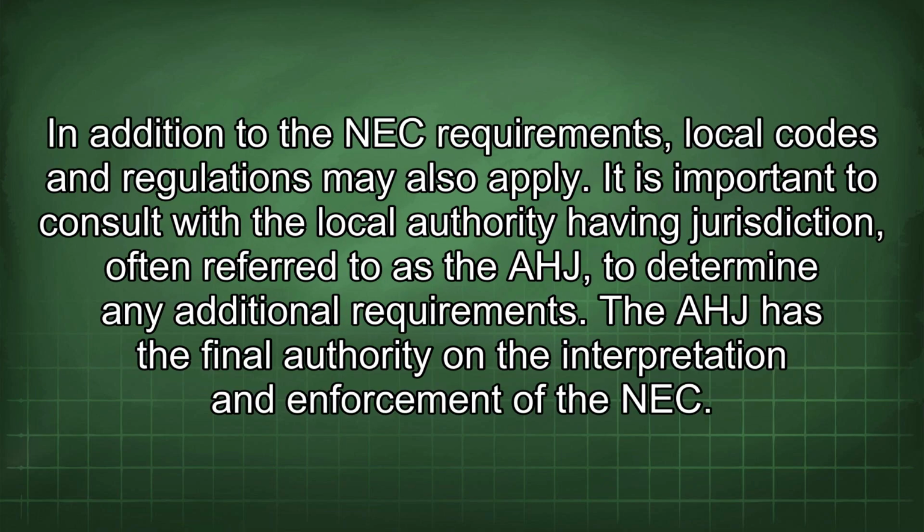In addition to the NEC requirements, local codes and regulations may also apply. It is important to consult with the local authority having jurisdiction, often referred to as the AHJ, to determine any additional requirements. The AHJ has the final authority on the interpretation and enforcement of the NEC.